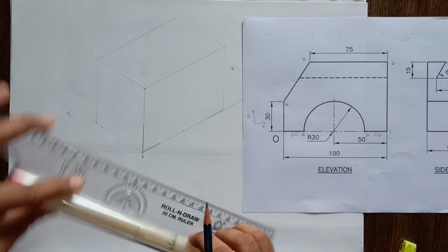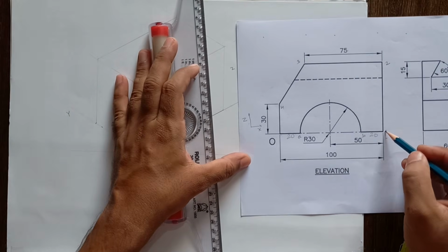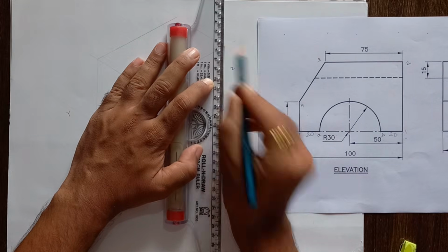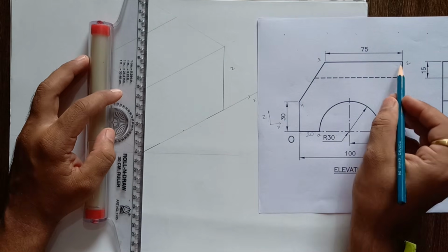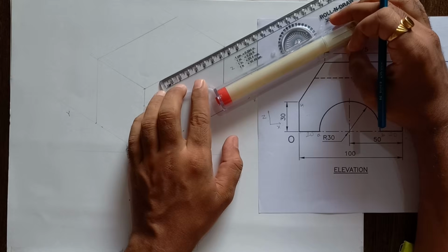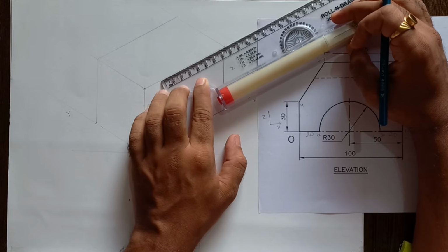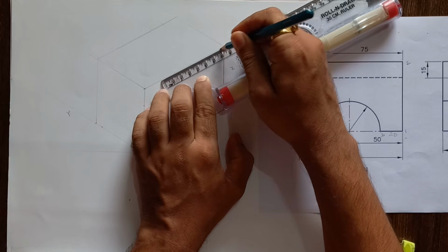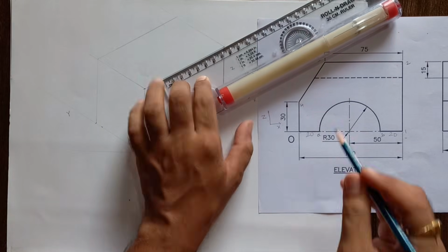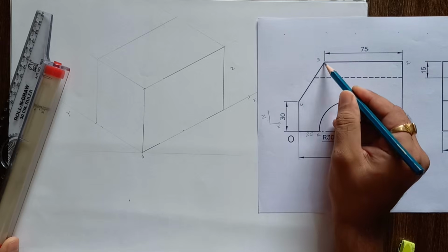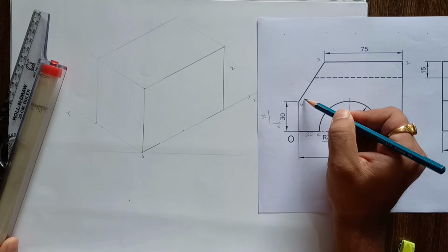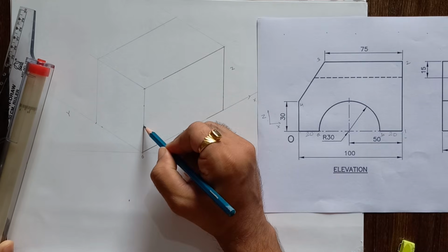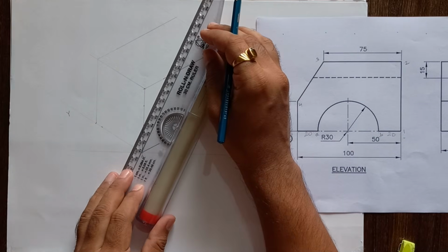Now this O2 to H is 70 mm. Sorry, 1 to 2 H distance is 70 mm. And this line is going to the Z direction. Then 2 to 3 is 75. This 2 to 3 line is going to the reverse x direction. This is 75. Now here 3 to 4 line is a non-isometric line. Angle is not given for 3 to 4. But here we have the point number 3 and point number 4. Directly we can join point 3 and 4.